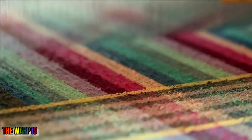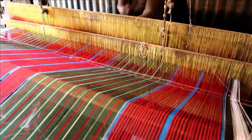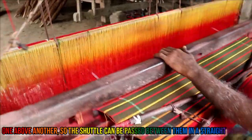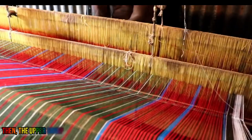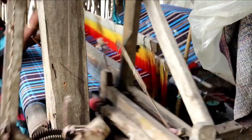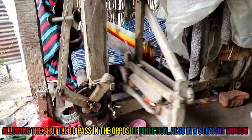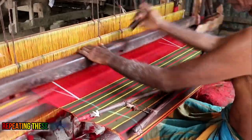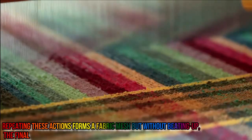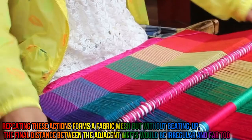The warp is divided into two overlapping groups or lines that run in planes, one above another, so the shuttle can be passed between them in a straight motion. Then the upper group is lowered by the loom mechanism, and the lower group is raised, allowing the shuttle to pass in the opposite direction, also in a straight motion. Repeating these actions forms a fabric mesh, but without beating up, the final distance between the adjacent wefts would be irregular and far too large.